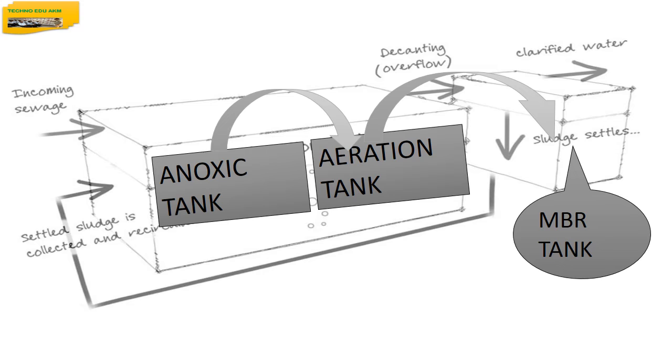Excess sludge wasting from the MBR tank. Centrifuge operation and disposal of sludge. General maintenance of equipment. Proper disposal of treated water. Maintain the logbook and report to your seniors in time and in proper way. Maintain good housekeeping at sites.